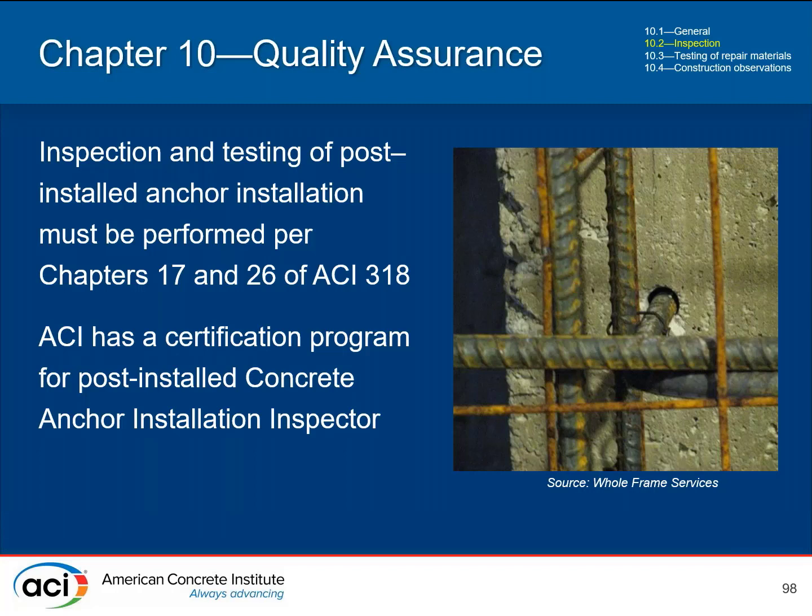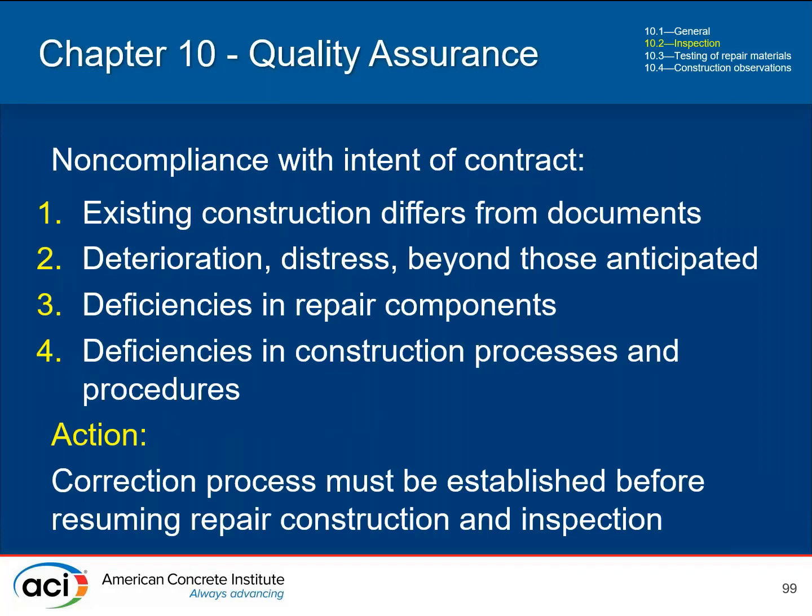These should be inspected by a certified anchor inspector, and ACI does have a program that you really should require the person inspecting the anchor installation to have been through, so that they know what to look for and what a correct anchor installation is, and are familiar with it. So those are two aspects from the inspection viewpoint that are not unique to repair, but can be very important in the repair industry. You should keep those in mind.